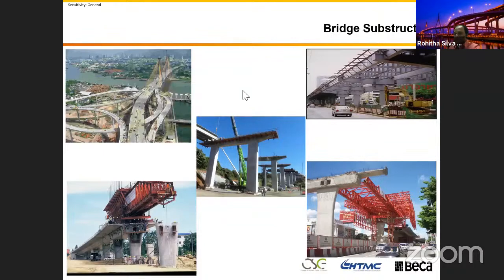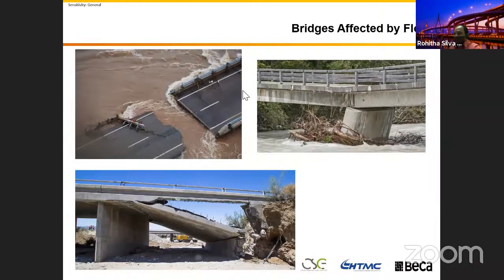And the bridge substructures, I think we discussed, we saw these pictures all together, the columns and the cross beams. I put this one here for you to keep in mind: when you are designing bridges, it's not designed for traffic load. You hardly hear of bridges failing due to traffic load. If they fail because of traffic loading, it's not because of the weight of the traffic, but because of instances like fatigue and other issues. But you can see what nature can do to our bridges.